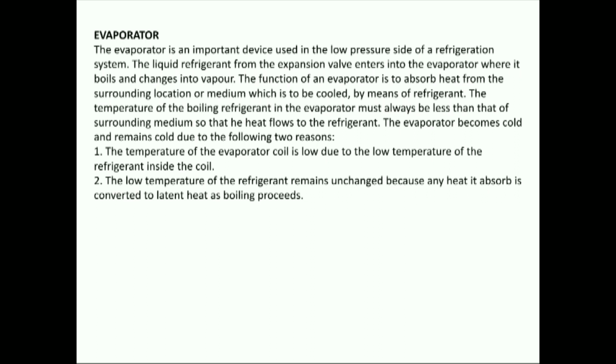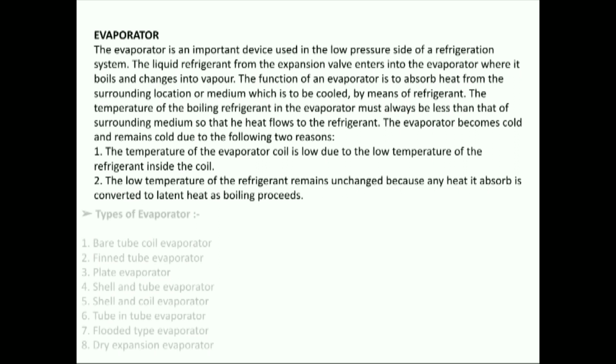The function of an evaporator is to absorb heat from the surrounding location or medium which is to be cooled by means of refrigerant. The temperature of the boiling refrigerant in the evaporator must always be less than that of the surrounding medium so that heat flows to the refrigerant.